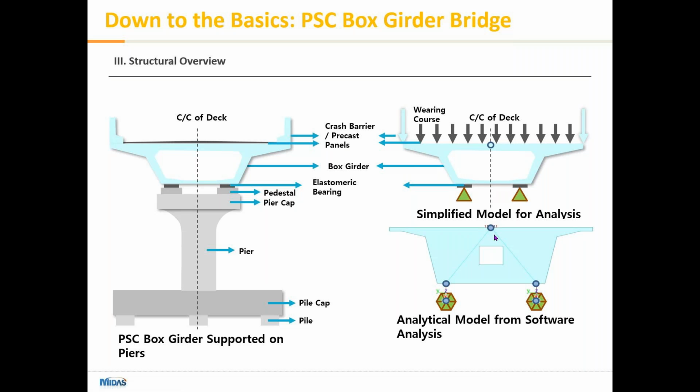As you know, when we model a particular section in any finite element software, the section can be represented in terms of a beam element, and the beam element will be passing through the CG of that particular section, right? So this is what we call center modeling.